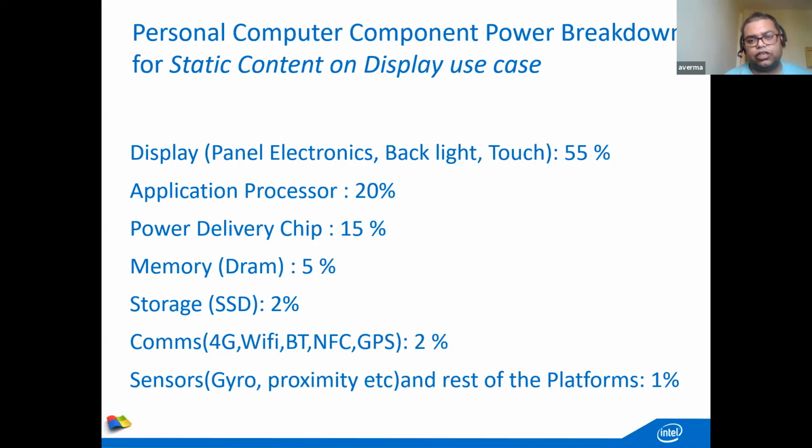So I just wanted to show that different components may take different powers, and that's why we need to ensure that these components are taking only as much power as required, or is optimal in the design, or their drivers are optimized, or their firmwares are optimized, or the way things are implemented is proper. Otherwise it may happen that your display power is very high. For example, in the case of display, you might have observed that when your background is black, your backlight power can be modulated and it can be low. But if that is not working, your actual display power can be quite high.